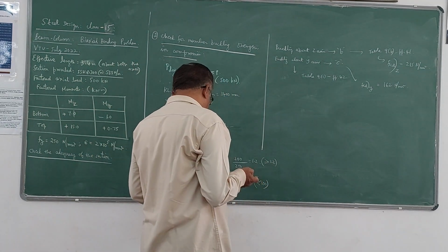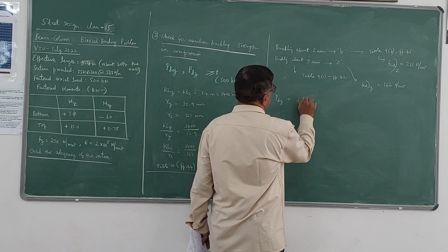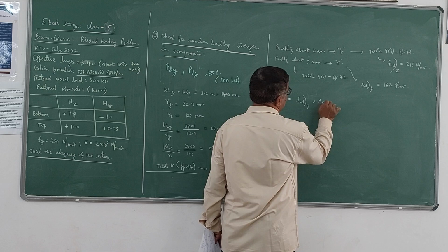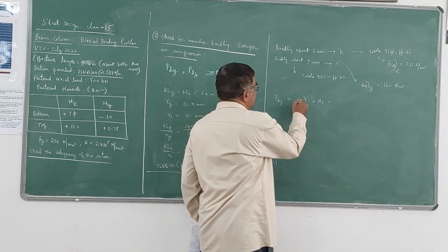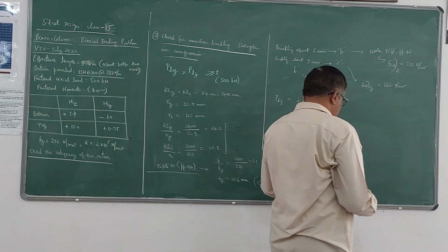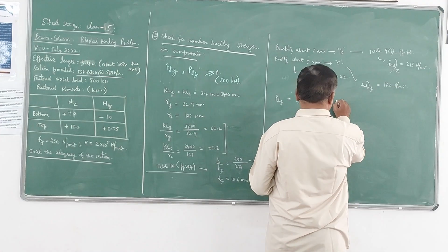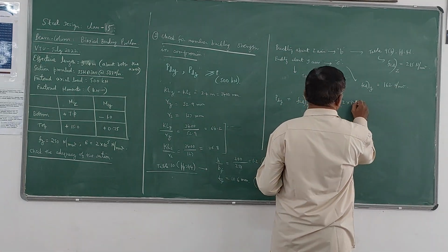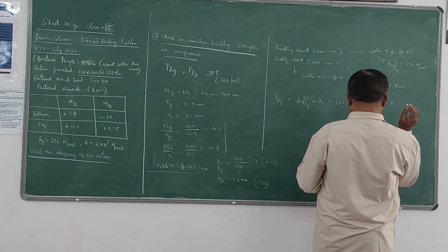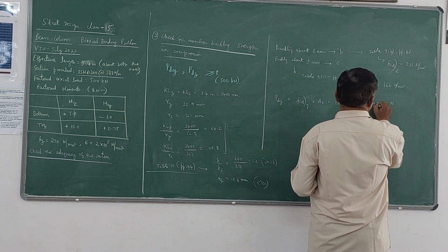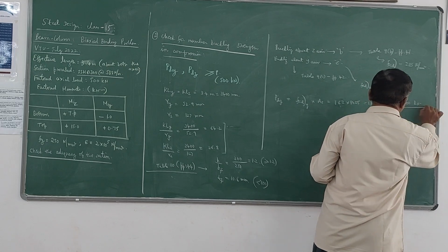Now once you get these values, if you want PDY, this PDY is given by FCDY into the cross sectional area of the section. So this is stress multiplied by the area gives the force, that is the design compressive strength along the y direction. You are going to get the value as 162 into 8025, which is the area. You will get the value in Newton. So it will be 1300 into 10 power 3, or you can write as 1300 kilonewton. So this is the value of PDY.